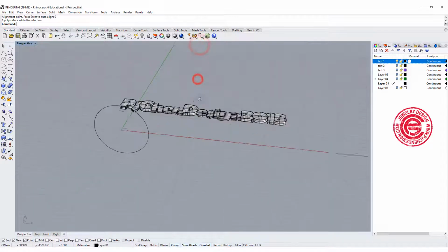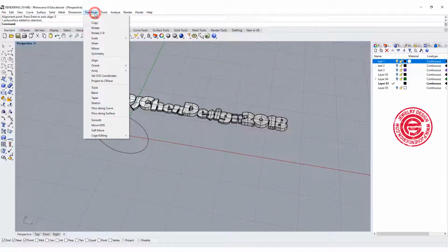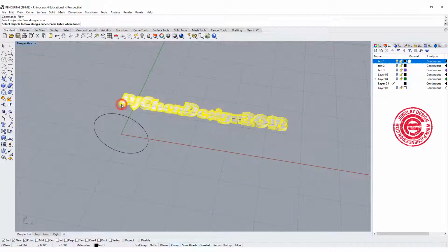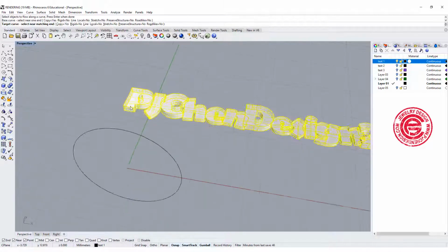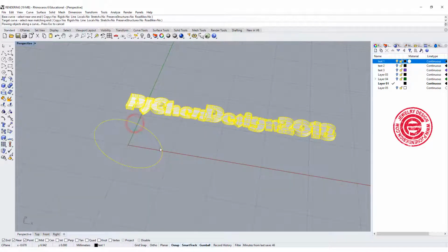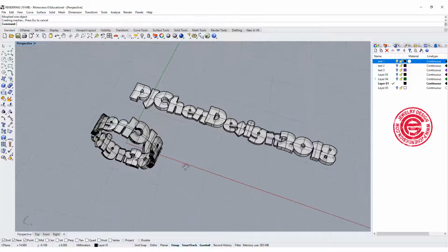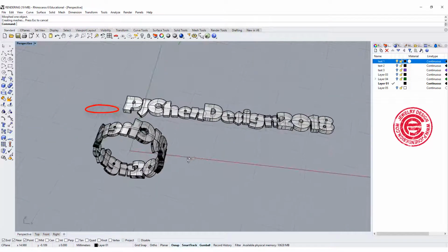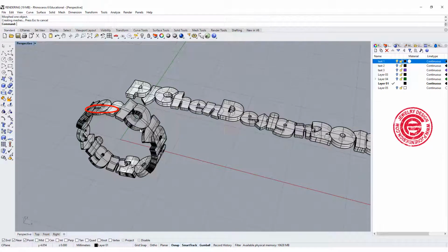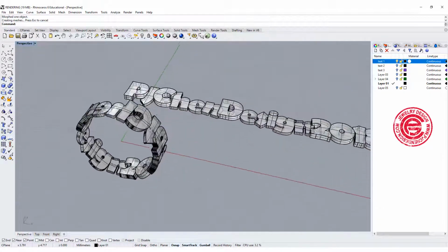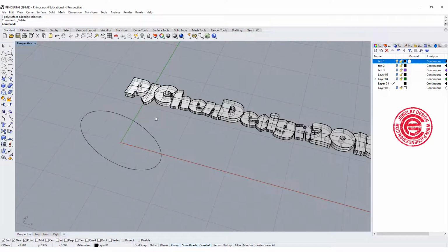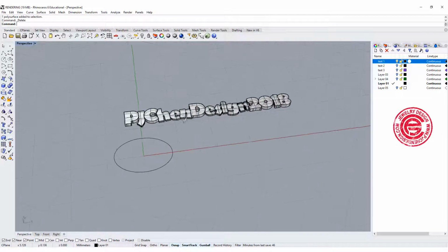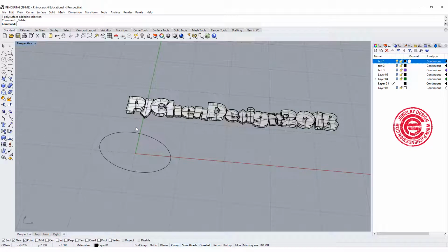So let's take a look at the perspective view one more time. This time, let's use the command. Under Transform, you have Flow Along Curve, and we want to pick up the text, and then zoom in to pick up the curve. We're going to come in here to pick up the curve here. So let's take a look. All right. The reason it is backward and is also cutting inside of the ring is because the direction of the curve that I picked is opposite to the curve that we built originally.